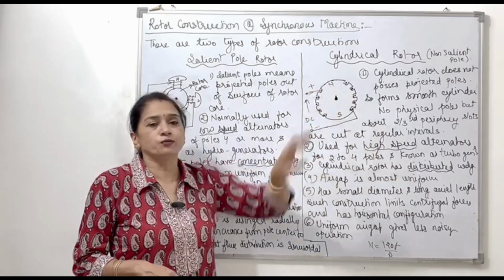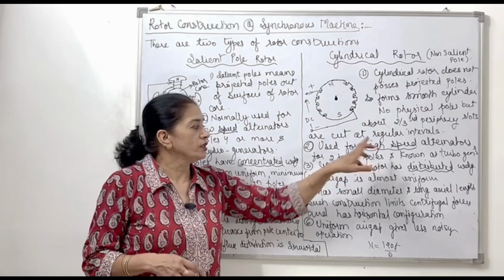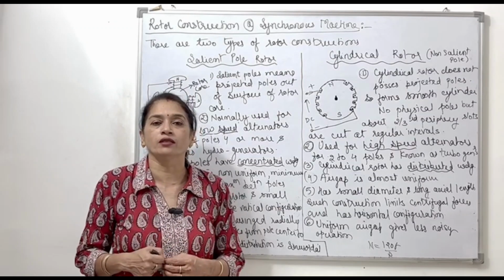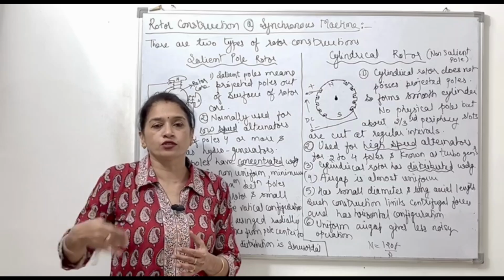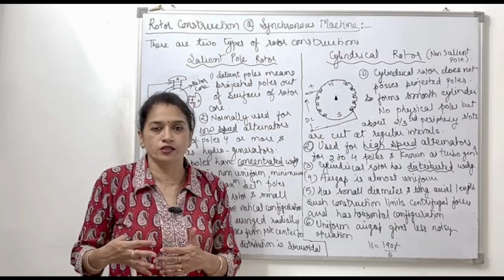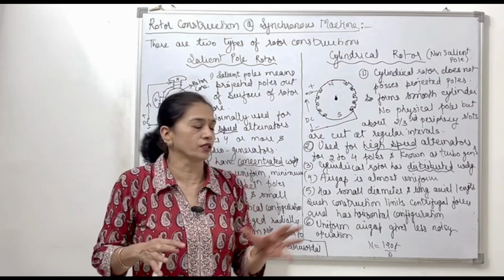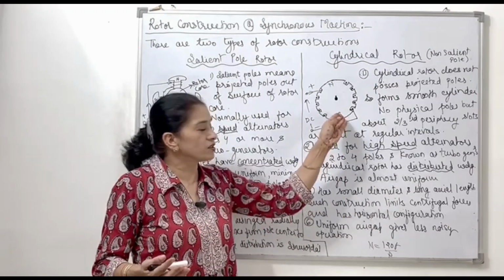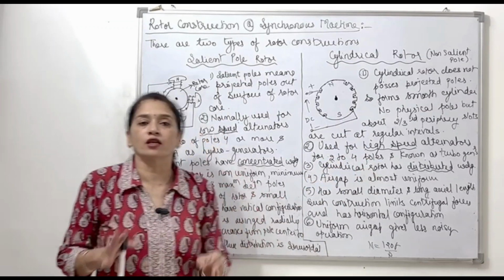Similarly here, these alternators which have a smooth cylindrical rotor structure are of high speed, and certainly high speed alternators are run by the steam pressure. The turbine receives the pressure of the steam through the jet. Those turbines consequently turn the rotor of the alternator. That rotor reaches the highest speed because of the steam pressure, and these alternators are made up of a smooth cylindrical structure. Now as speed is high, the number of poles would be less. So these structures are made with either 2 poles or 4 poles, and these are known as turbo alternators.